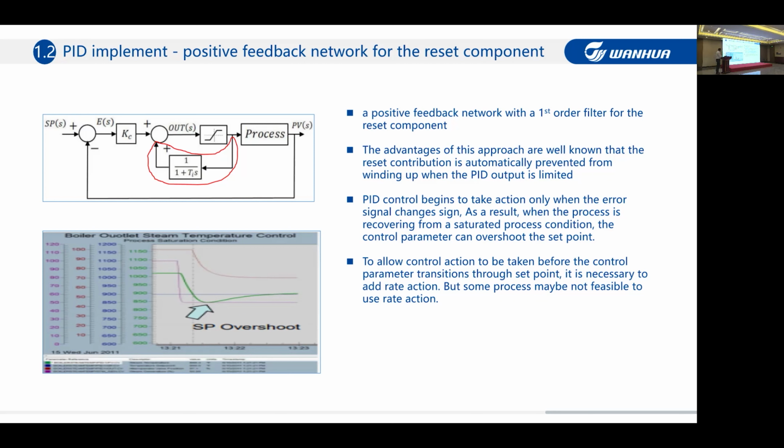But this arrangement still has its shortage, because the reset function will not be released until the proportional part changes the signal, which means from negative to positive or positive to negative. Only after the proportional part changes the signal does the reset start working.